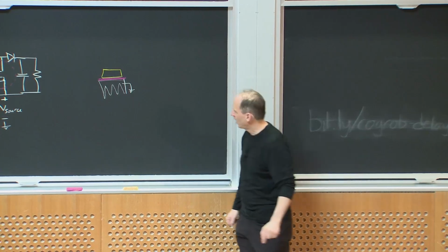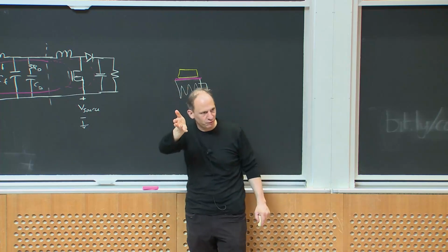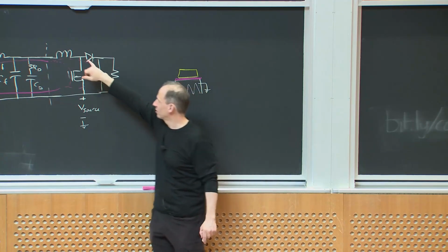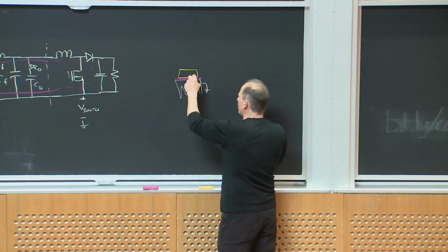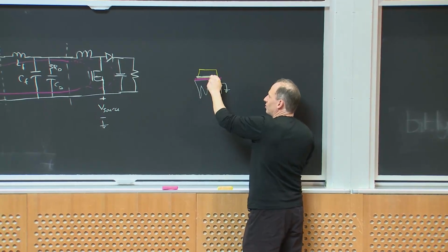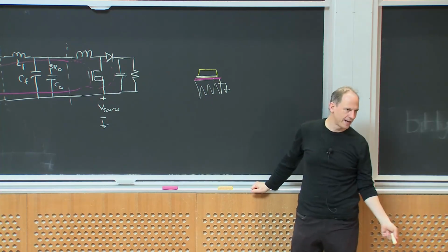If I think about a transistor, what's the package of the transistor, if you have a TO247 or a TO220 or something, that's actually the drain node of this thing. So what I have is essentially a piece of metal here, a thin insulator for electrical insulation, and then a ground. So what is that? That's a capacitor.